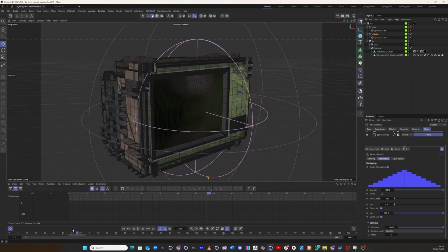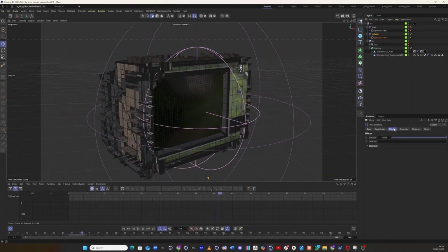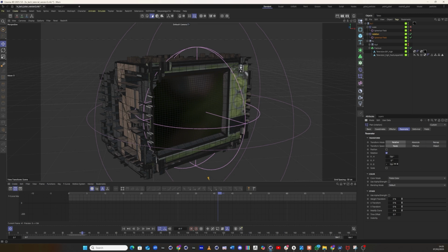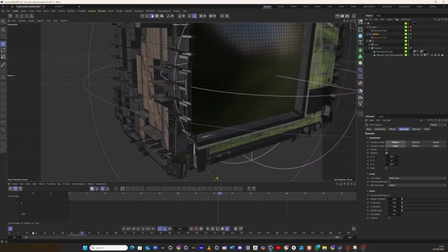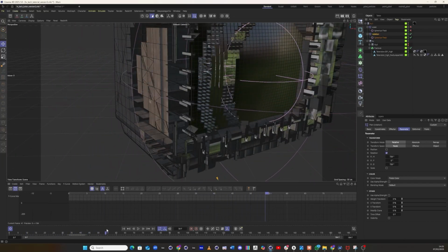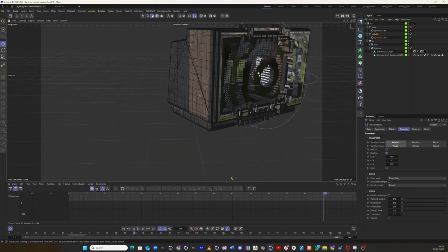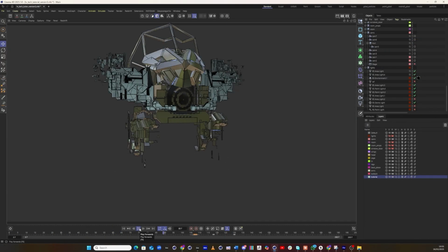When you divide the total rotation, 720 degrees, by the number of steps, 8, you get 90 degrees. This means the movement will snap to precise 90 degree increments as it follows the spherical field, creating a more technical, controlled animation. Now, let's shift our attention to the other robotic elements visible in the scene.